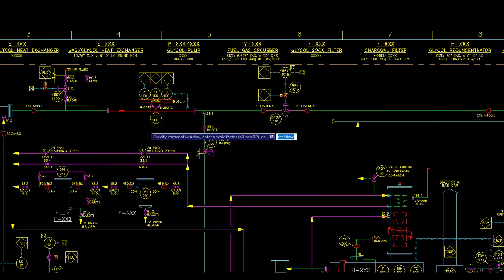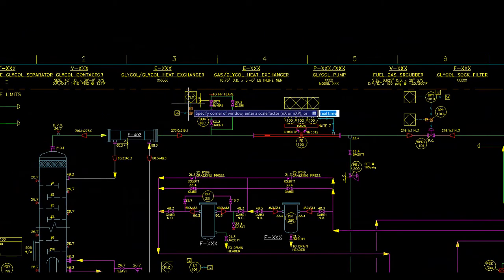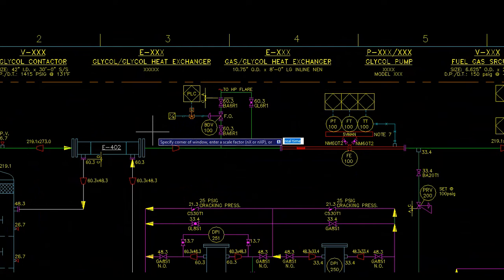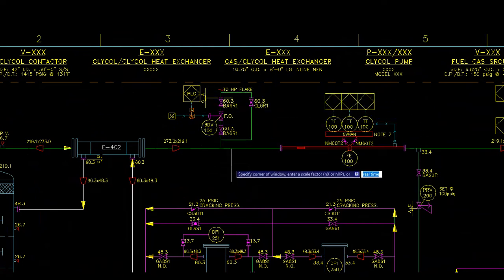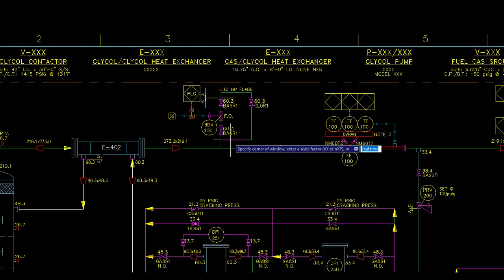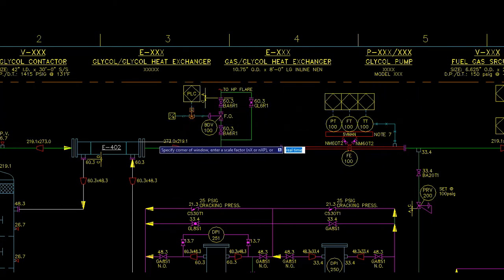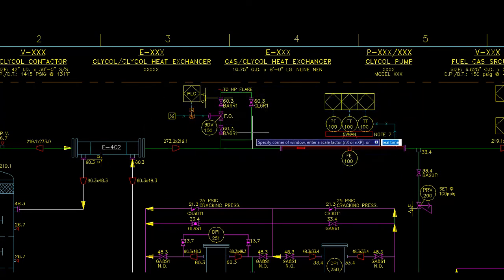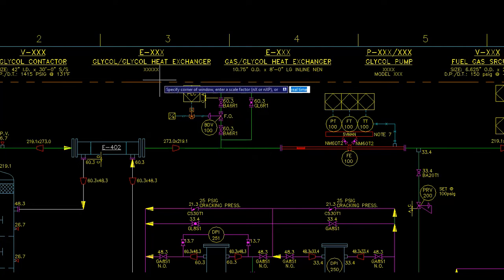Notice there is a blow-down valve here that will depressurize the contactor to 50% of its pressure, or 100 pounds, in 15 minutes. This is a standard mentioned in API 521. If you want more details about that, you could go there. A process engineer is required to follow this code in designing all blow-down valves of pressure vessels.